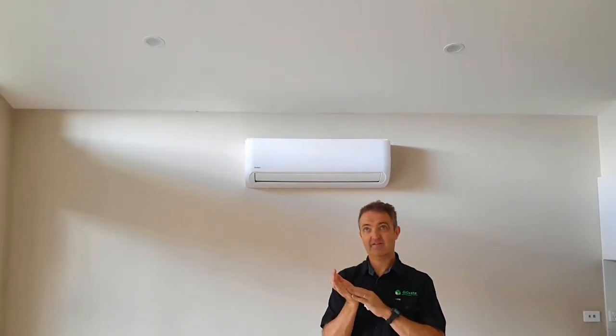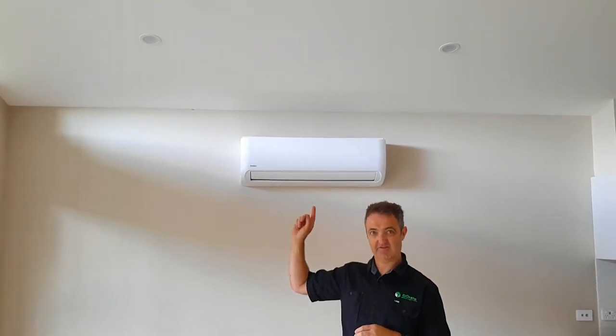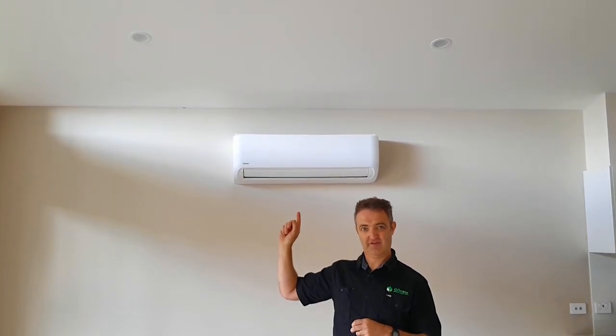But one existing point of weakness in most houses is the downlight, so it's really worth looking if you're doing an existing house as to what sort of downlights are in there, and if you're building a new house, make sure it's an IC rated one with a good gasket.